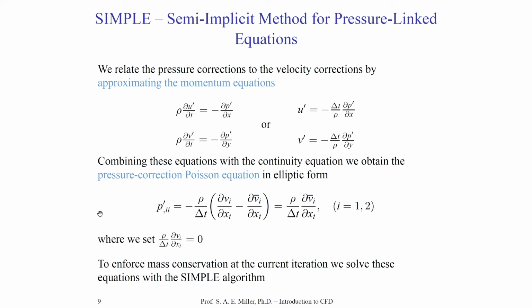Now, we'll try and combine these particular sets of equations with the continuity equation. So we decompose the momentum equation with the corrector step, and now we're going to insert it and combine it with, of course, the continuity equation. This is the so-called, and what we find, the rather popular pressure correction Poisson equation, named after, of course, the mathematician, but he didn't find this equation. It just has a similar form to his, of course, famous PDE, which also carries his name.